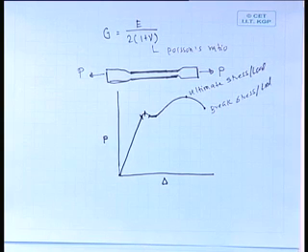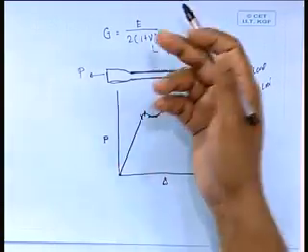So, it should be load and load instead of stress, but we loosely express that part in the form of stress also, because stress is load by the area. But if you cross beyond this ultimate load, your area will be significantly reducing, but we are not taking that actual area, how much it will be there after reduction.